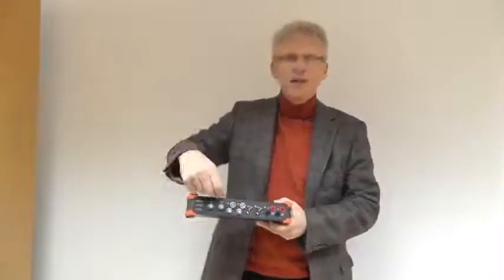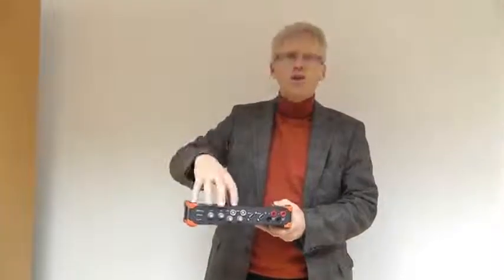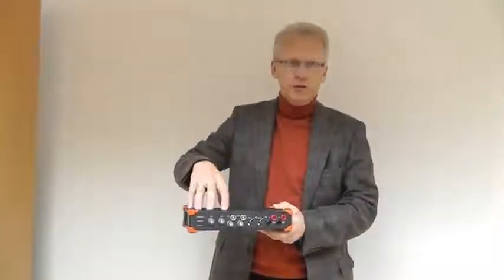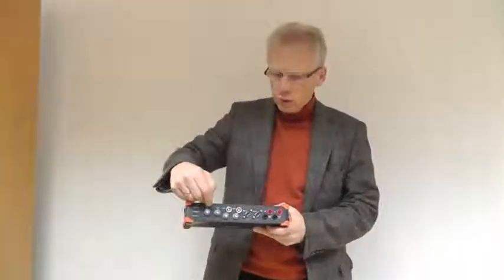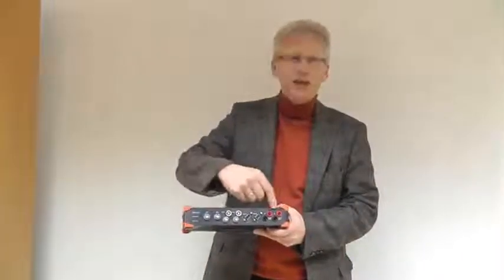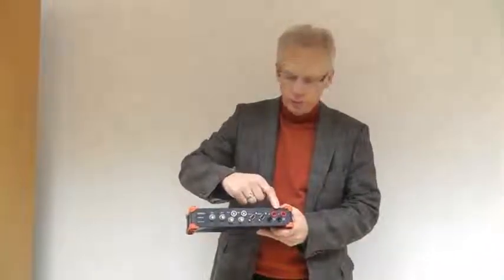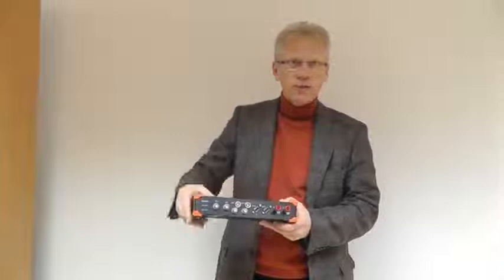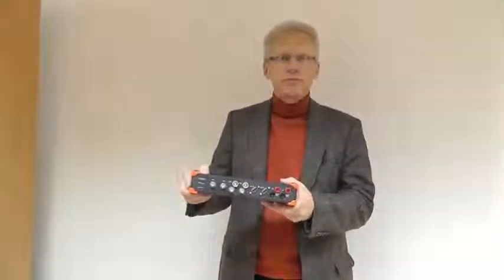Look at this. We have several input channels and you connect any sensor. You don't even need to know what kind of sensitivity. The dual core technology running two ranges will take care of that. You just connect, you measure. You have small signal inputs, you have high signal inputs, microvolts or high voltage, vibration, counter, whatever. That's it, and we will show you how you're going to use that in a minute.